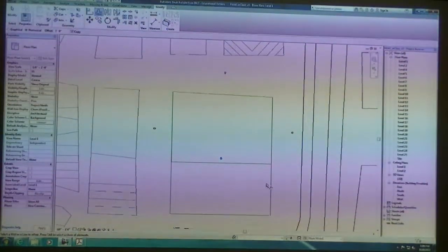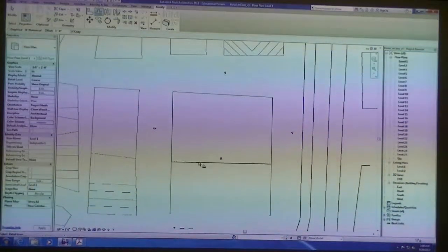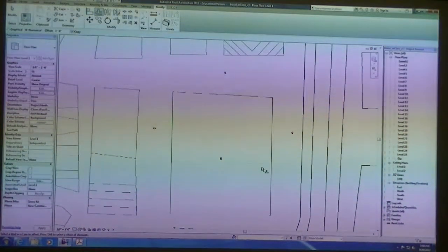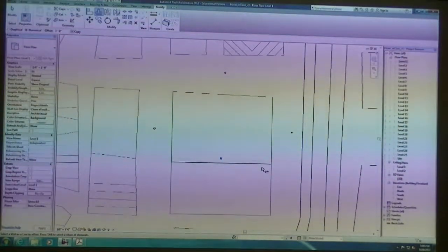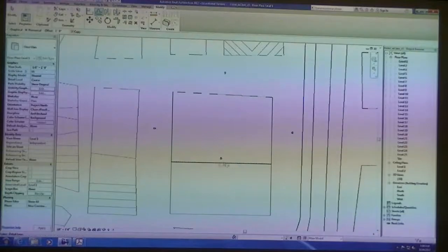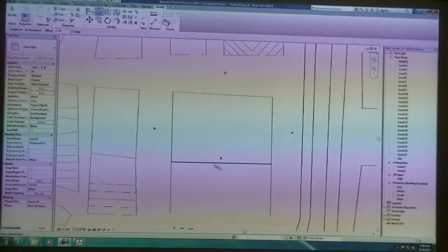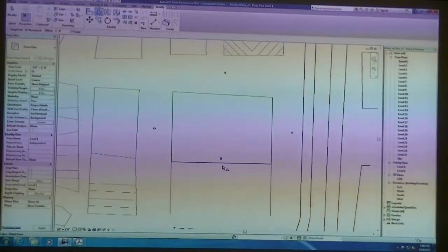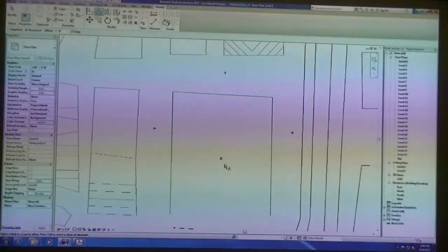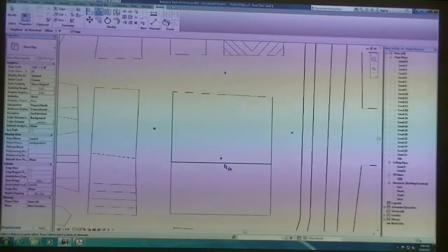Now, I know that this building has a wall that's on this north side of the site, and this has a lot of glass. You can imagine this whole entire tower has glass on all 4 sides. So when we build our tower, we're not going to want to build right up against this particular building. And actually by code, we're not going to be able to, because there's such things as fire separation distances.